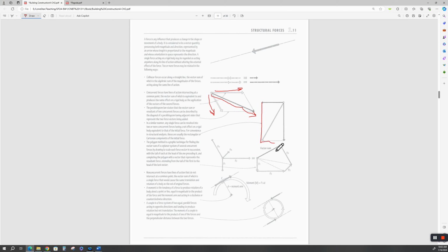if that was a structural member and that was a structural member, and I had another structural member over here, okay, and this was a structural member, what would that look like? That would look like a piece of a square truss, like an old Pratt truss or something, right? Or a Warren truss, or a railroad truss, all right? And so all these forces would be going this direction, and when they reverse, they'd go that direction. This would be in compression. That might even cycle back through tension if we had a force reversal. So that's all this is representing.